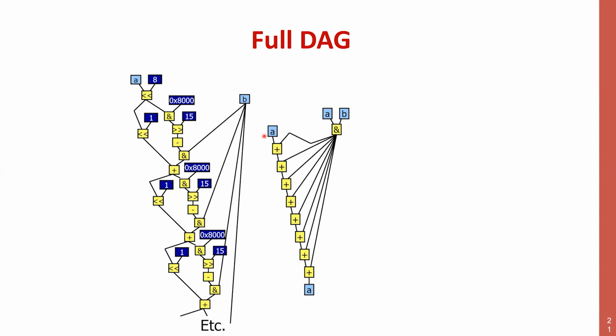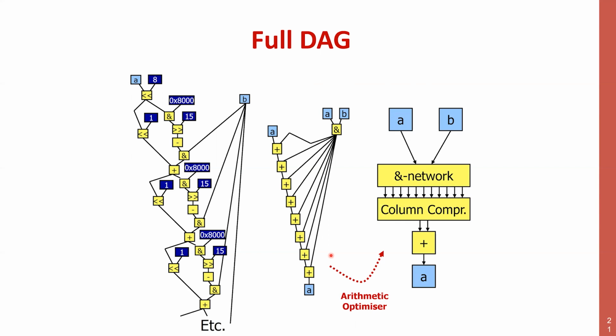And here you have 8 addenda that you have to add. So 7 times, you can use one of those carry save adders to do the addition, and you can do it extremely efficiently, in more or less a binary structure like we have just seen. Only at the end, you'll find yourself with 2 results, and for adding the last 2 addenda, a carry save adder is useless, so you need to buy yourself a normal adder. So this means that if you do some tricks in arithmetic, what you have is a network of additions that are these.